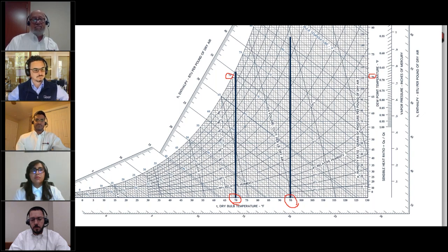Yeah, good question. All right, next one. When the wet bulb temperature equals dry bulb temperature, what do we infer from that situation? Or will that ever happen? In that situation, we're at saturation, which means that we are at 100% relative humidity. Yeah, that's a good question. That would be something like, I don't know, the other morning it was 60 degrees wet and dry. That's foggy outside. So 100%, you basically have fog. Gotcha. Good question.